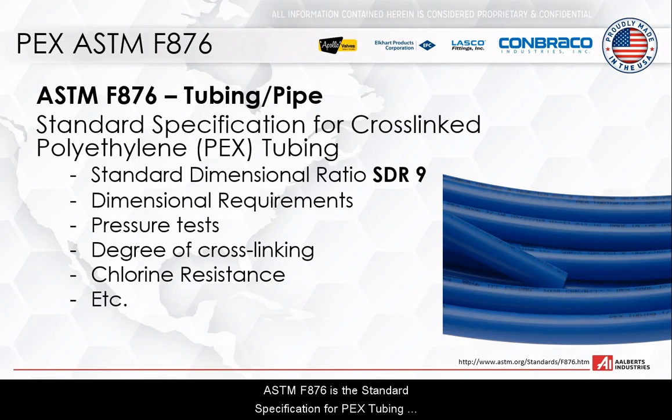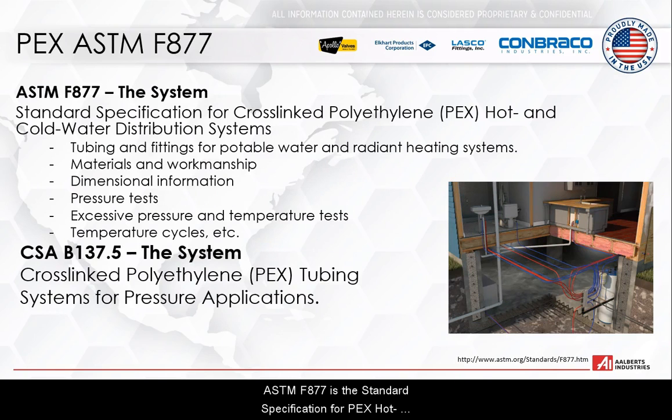ASTM F876 is the standard specification for PEX tubing, and it defines performance characteristics for the tube. ASTM F877 is the standard specification for PEX hot and cold water distribution systems, and it defines performance criteria the entire system has to meet. A similar standard is CSA B137.5.